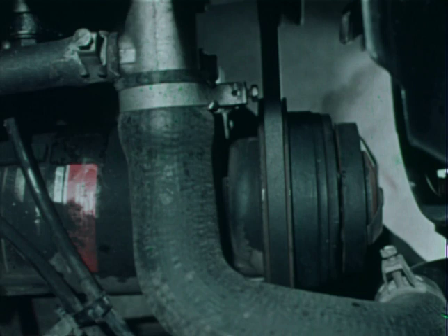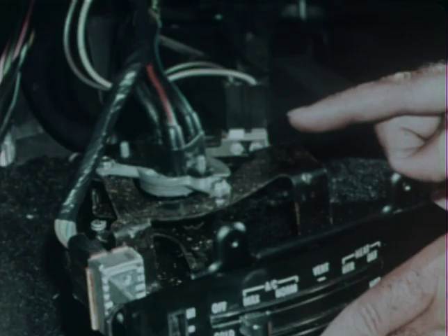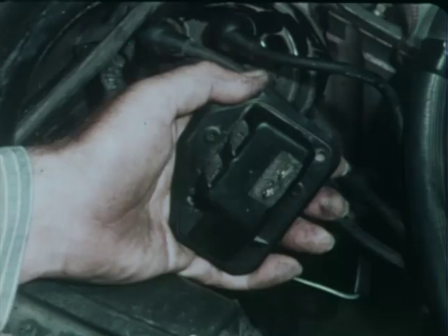The compressor is driven by a belt off the engine crankshaft through an electromagnetic clutch when current flows to the clutch coil. The entire refrigeration process is halted by interrupting the clutch current, which can be accomplished by any of three devices. First, there is the compressor switch at the heater and air conditioner control panel that must be closed for clutch current flow. Next, there is a thermostatic switch that cuts off compressor clutch current when the evaporator temperature drops to near freezing to prevent ice from forming on the evaporator tubes and fins.